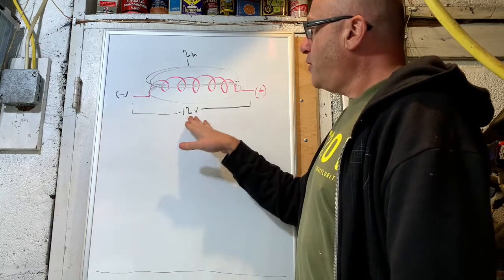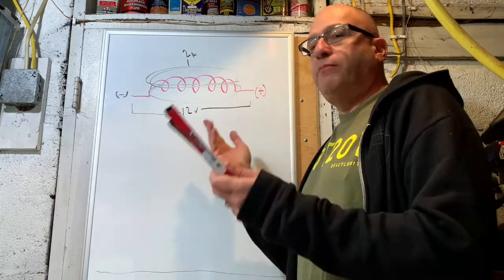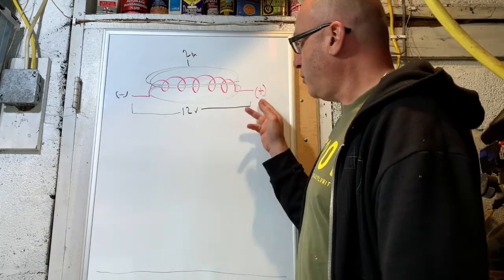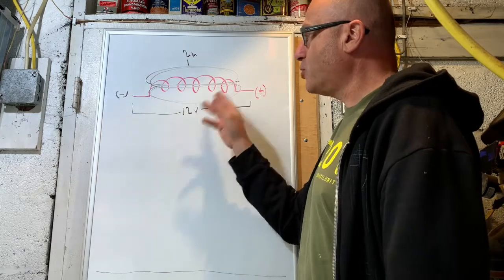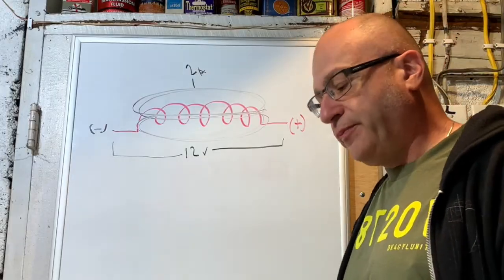And you know, this 12 volt signal would be sent from the computer. Probably it would always have power on one side. The ground would be controlled from within the control unit inside the computer.